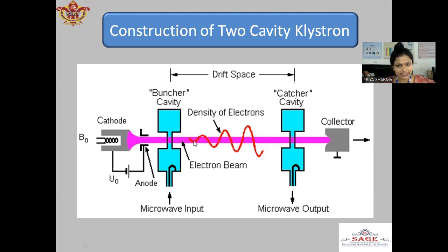This is point A, this is gap B, and this is point C. Similarly, an early electron that passes through gap A slightly earlier than the reference electron is subjected to a maximum negative field. Hence, this early electron is decelerated and travels with a reduced velocity.